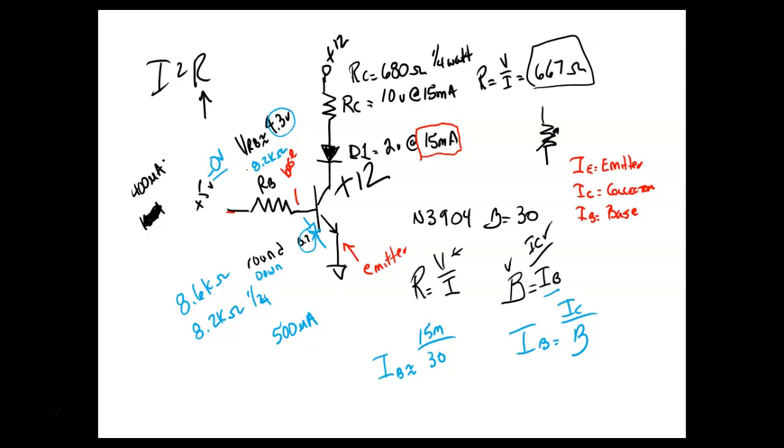Are we okay? This could be a switch. It wouldn't make much sense to use a transistor to turn on something that a switch would do. But a switch takes somebody for you to turn off and on, right? This guy right here, we're turning this thing off and on electrically. So where does the 5 and the 0 volts come from? It could come from a sensor. It could come from a photovoltaic cell, even though we don't have one that puts out 5 volts. Could be coming from a thermistor. And then now we're electronically controlling it. So any questions on this, guys?